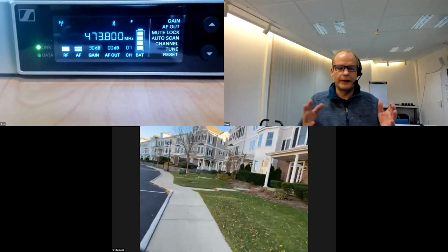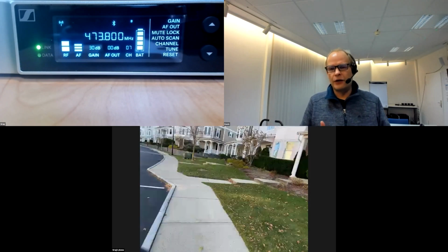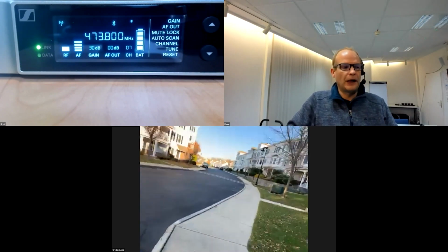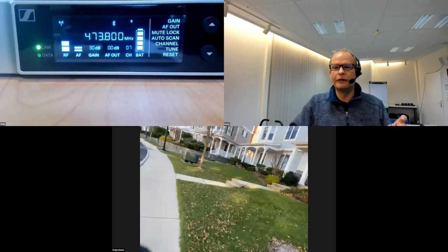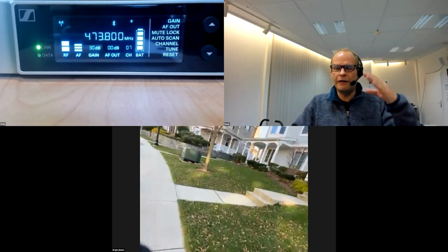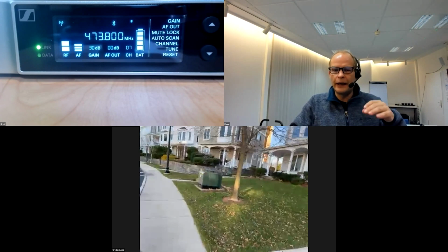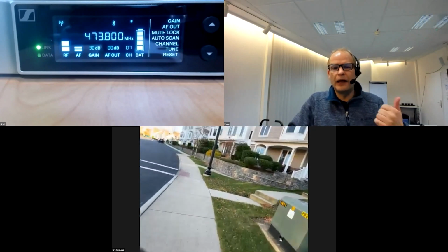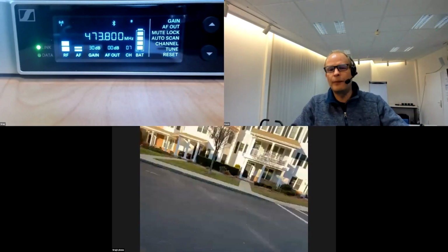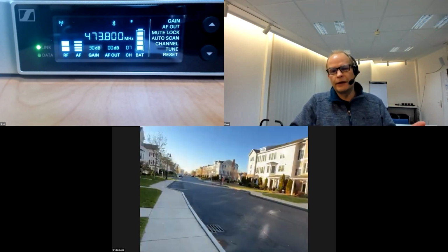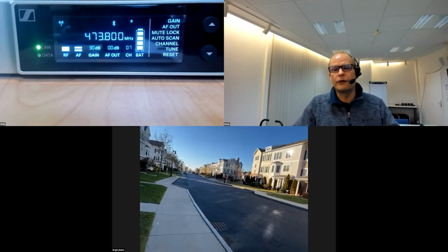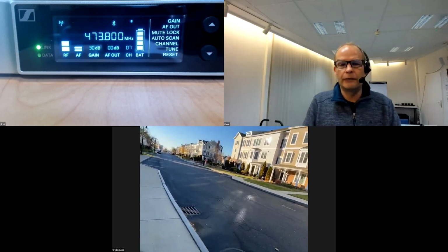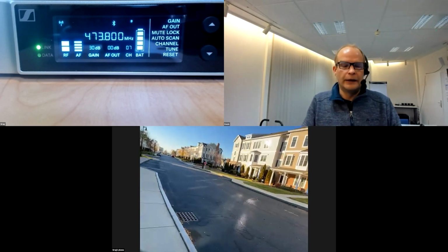With a digital system, it's entirely different, because the information is not stored in the amplitude, but in the phase of the carrier. You need around 10 to 11 dB over the noise. So that means you can have a much lower signal, and you still have CD quality audio just because it's digital. In the analog domain, you would start now to hear a little bit of noise coming up, like swooshes and all these things, and that's simply because the signal to noise in the audio is massively dropping down because of the reception of the RF signal. In the digital domain, different story.